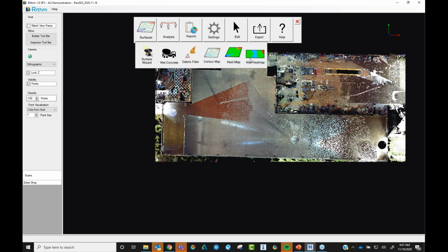Now, also, besides that, I'm going to talk about this heat map here a little bit more in a second. If we choose to do a heat map on a floor or a heat map on a wall, we can actually take that data and export it to an XYZ laser scan that we can take through Recap and then bring into Navisworks. So if you wanted to show that kind of heat map of maybe how a wall is bowing or how this floor is deviating right over the point cloud, you can do that. That's very powerful.